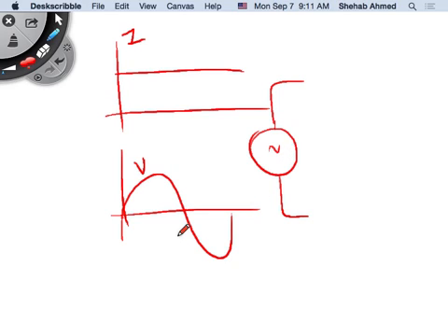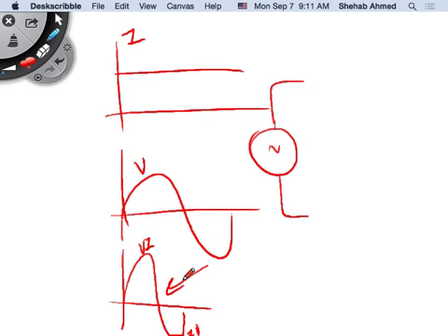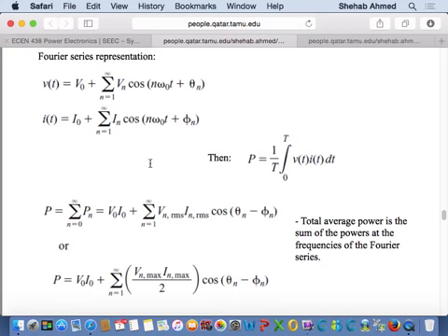And we have to go back to our basics, right? What is average power? It's the integration of instantaneous power. Instantaneous power in this case is this multiplied by this. So it's the voltage waveform basically scaled, right? It's V times I here, V times I here, right? So what's the average value of this waveform? Yeah, equal magnitude. So it's 0. So anytime you have voltage and current that are not the same frequency, then there will be no power transfer due to that, right? And when does this happen? It happens a lot in power electronics, actually.